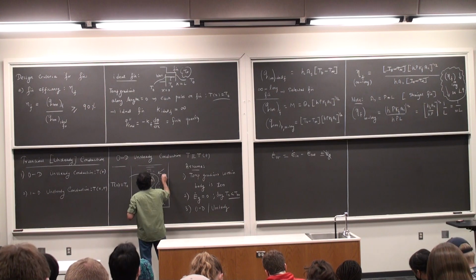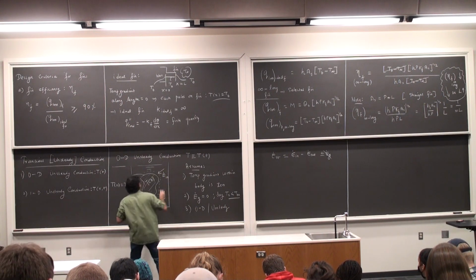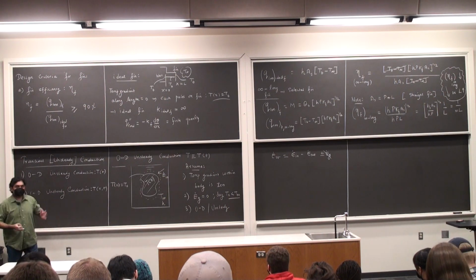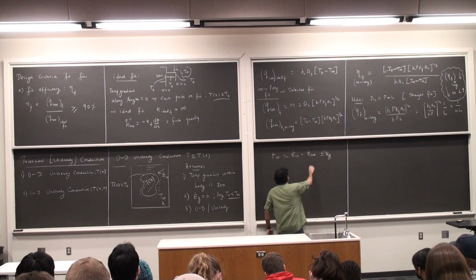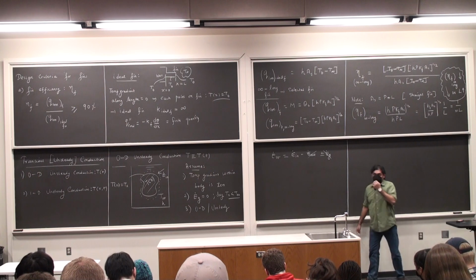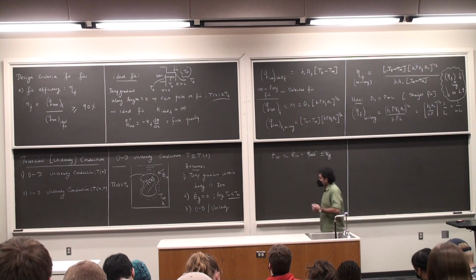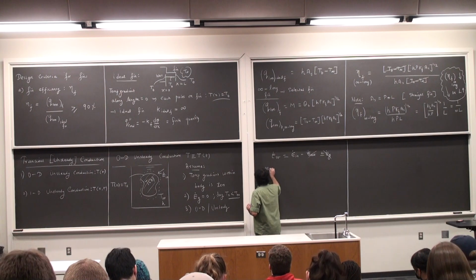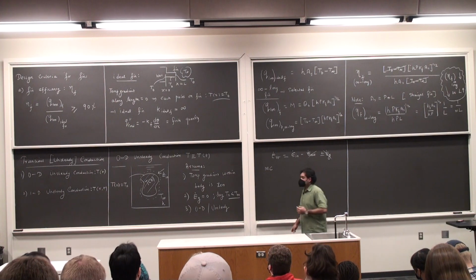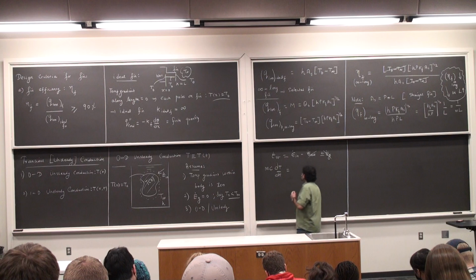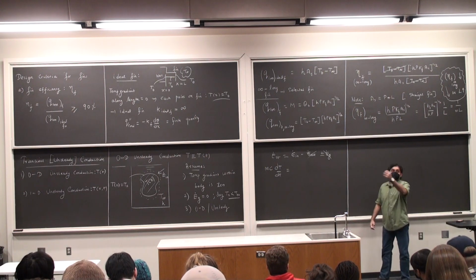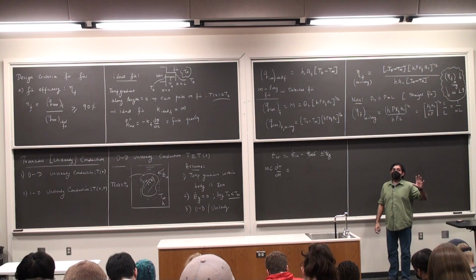There is E dot in, there is no E dot out. E dot in coming from all sides along the surface area. So E dot out is 0. And if I write E dot stored, which we have written as the rate of change of the stored thermal energy, this is mass times specific heat capacity, dT by dt. E dot in is the heat transfer from the ambient onto the body.